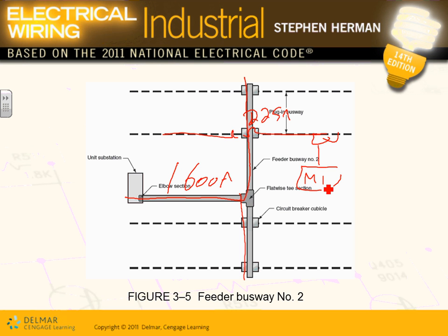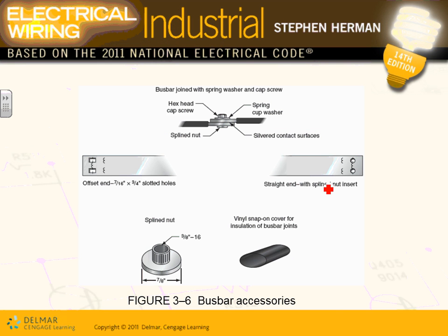Was it the cable tray then that will run with the low voltage? That's low voltage, yeah. It will look, in Revit, like the low voltage cable tray when you lay them out. It looks exactly the same, but it's actually a different family in Revit. We have plug-in families and feeder families in Revit when we lay out our feeders.